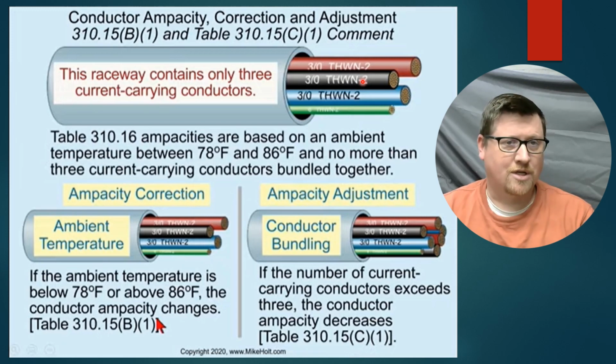And there'll be a couple on your test that are probably pulled out of that column. And then if it is less than 100 amps, then we're going to choose the 60-degree column. We're going to find our initial wire size in that column, and we've already done our padding for our continuous load.